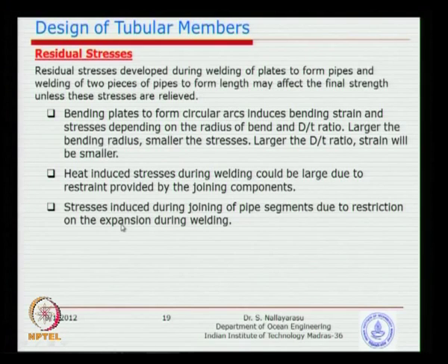Third, stresses induced during joining pipes with the main structure, basically like what I was trying to explain. You have two ends restrained, you take a piece of pipe, fit it there, and do the welding at both ends. You will see that stresses will be induced both on the parent structure as well as on the structure being welded.